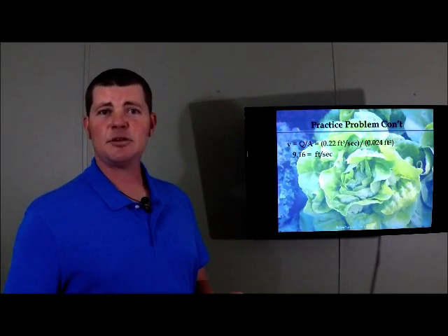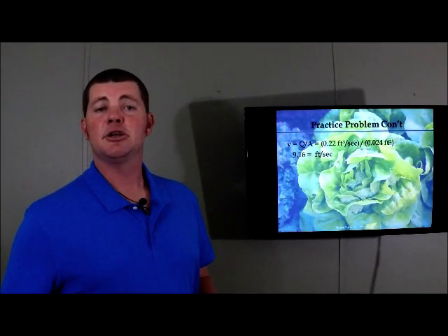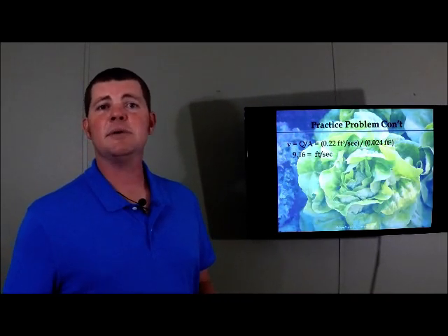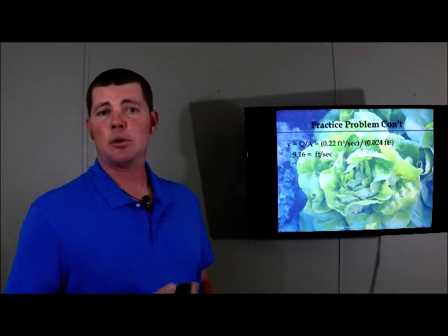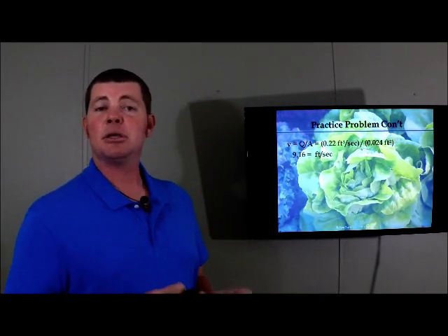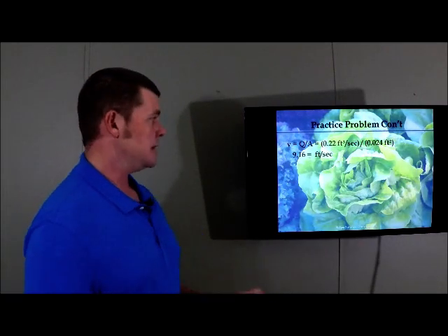So sometimes you have to do more than one calculation to assure yourself you're making the right decision, because it's almost never going to be the exact number that we want to shoot for. It'll almost never be exactly 5 feet per second, but you want to get as close to that standard as possible.